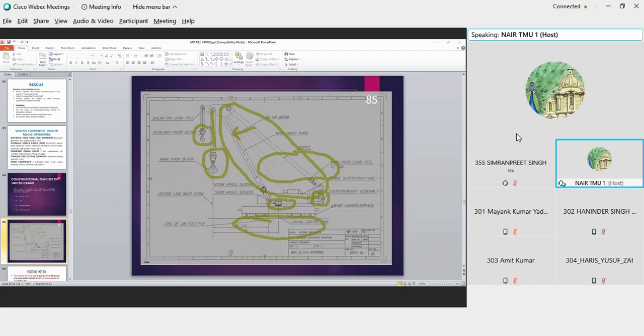Now what happens when this comes to an accident site? You will find that there is one more wagon which is connected along with this crane on which the jib is resting. So on an accident site, you remove this wagon on which the jib is resting. This wagon is removed and then you raise the jib and you prepare the 140-ton crane to start the restoration work.